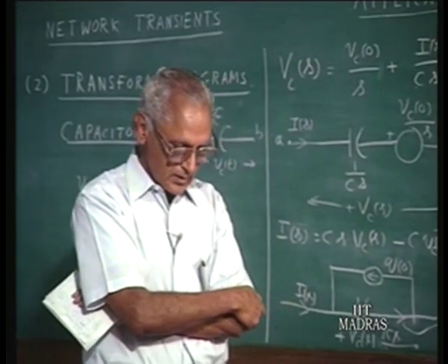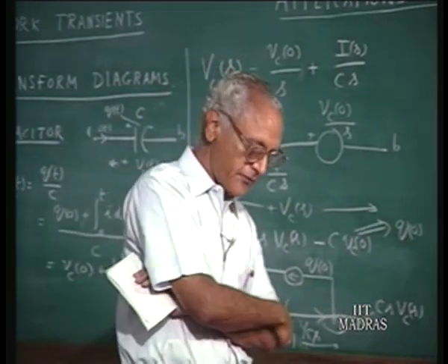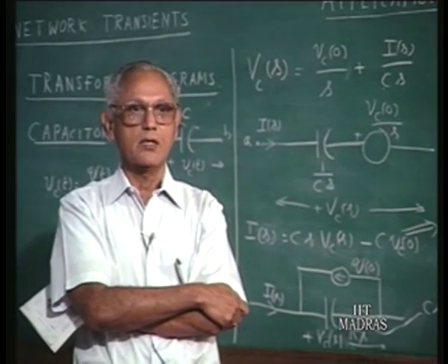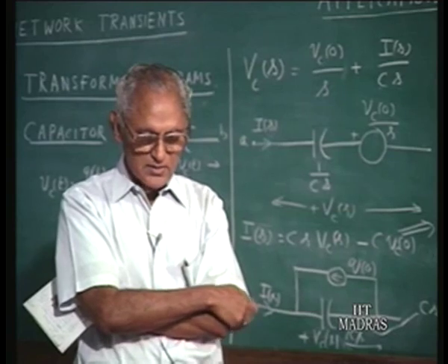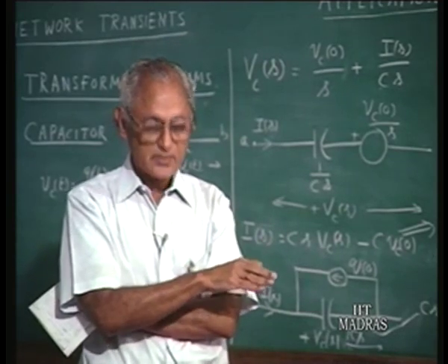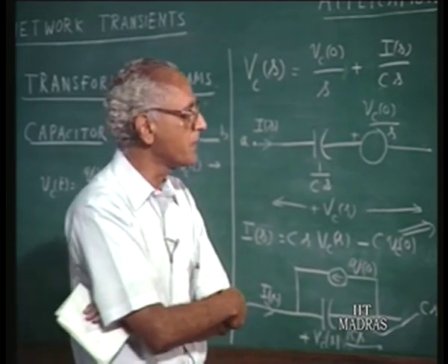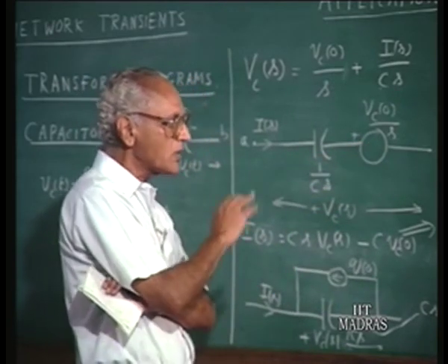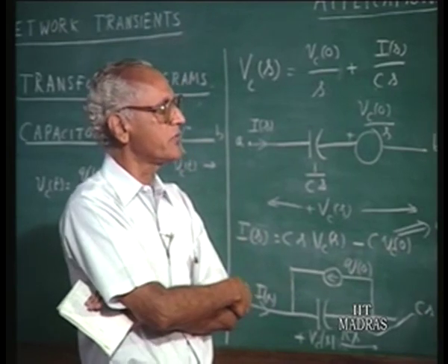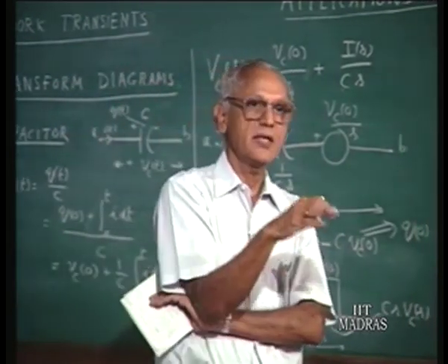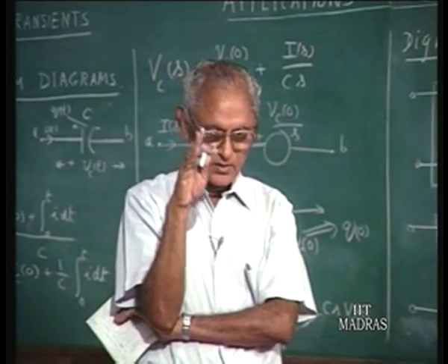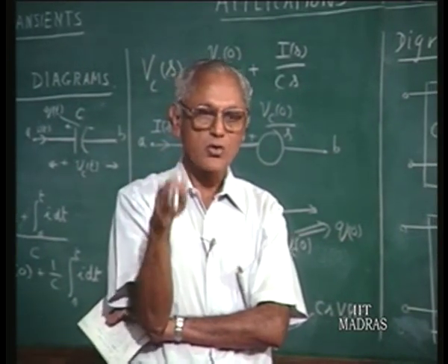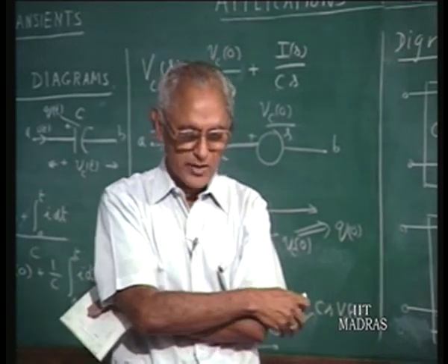problem, the effect of excitations or effect of sources on an otherwise unenergized circuit is what we are looking for. Because initial currents in an inductor and initial charges on a capacitor can be represented by equivalent sources, as we have seen. Therefore, without any loss of generality, we can think of a situation where we are considering the effect of sources on circuit elements which do not carry any initial current or initial charge, because those initial conditions can be replaced by equivalent sources.